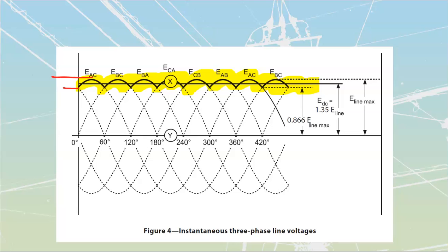If we go to a very large DC demand, whether that's going to be for a large VFD or for a large DC drive, we want the absolute minimum amount of ripple and the higher ripple frequency because it's closer to a straight line, right? If you go through a bunch of small bumps really fast, it's closer to that. You feel less than if you go over top of a large set of bumps.